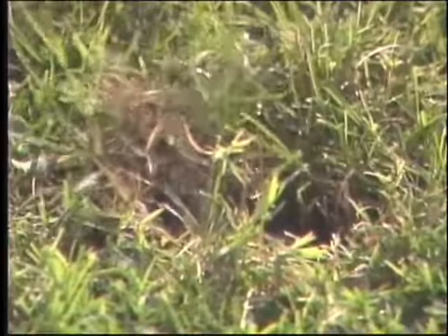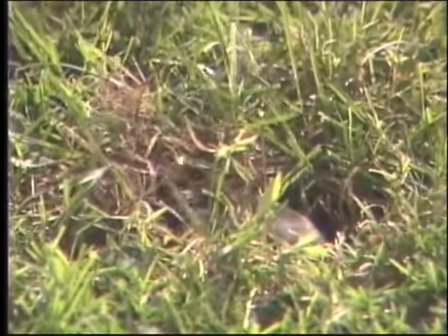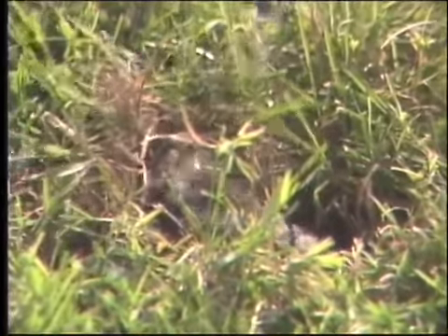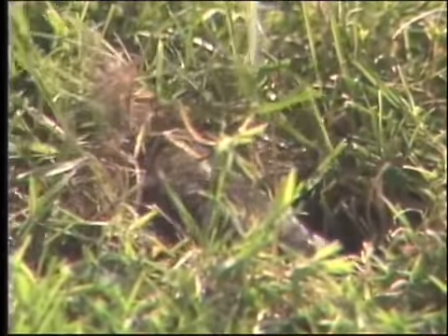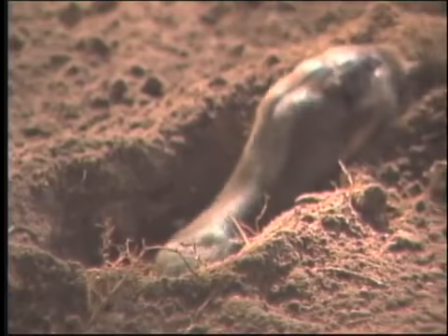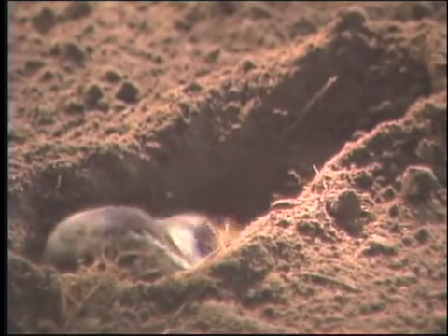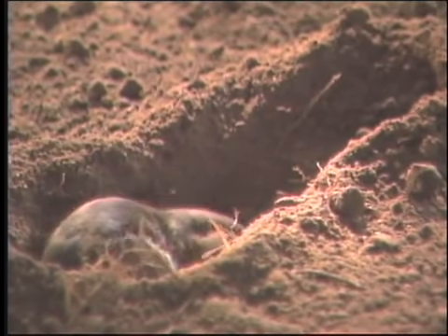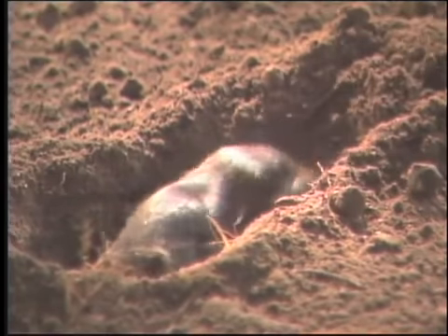Also, the chamber system is susceptible to certain types of damage. It is important to keep gophers, prairie dogs, and other burrowing animals away from the chamber system. If they burrow into the chamber, standing water such as irrigation or rain may flow through the opening from the ground level into the chamber, and the water may fill the chamber with soil, requiring replacement of the drain field.